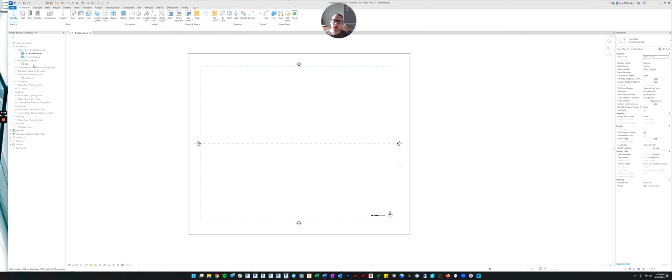Okay, let's open up a couple other views and then tile them like we did in the last video. So we want the floor plan. Let's look at an elevation. So let's see if they have an elevation here. Oh, look. So here's the category elevations. I'm going to click the button to expand it, and here's north, south, east, and west.